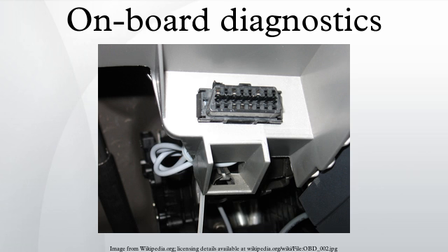Early versions of OBD would simply illuminate a malfunction indicator light, or idiot light, if a problem was detected, but would not provide any information as to the nature of the problem. Modern OBD implementations use a standardized digital communications port to provide real-time data in addition to a standardized series of diagnostic trouble codes, or DTCs, which allow one to rapidly identify and remedy malfunctions within the vehicle.